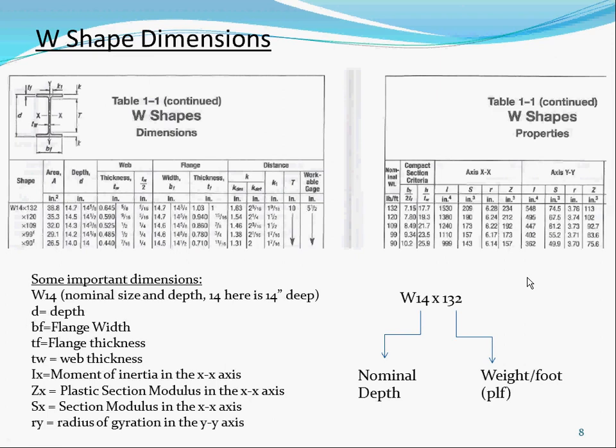And that's a lot of people price on that. The tonnage of steel is how much they weigh and how much they quote people. Yeah, but sometimes if you have a lot of different sections, handling different sections becomes costly. You would like to reduce it to certain sections if possible. But rule number one is to try to keep the shape, when you're doing the design, as light as possible, because that's what they price it in. They price the steel by the weight of the steel.